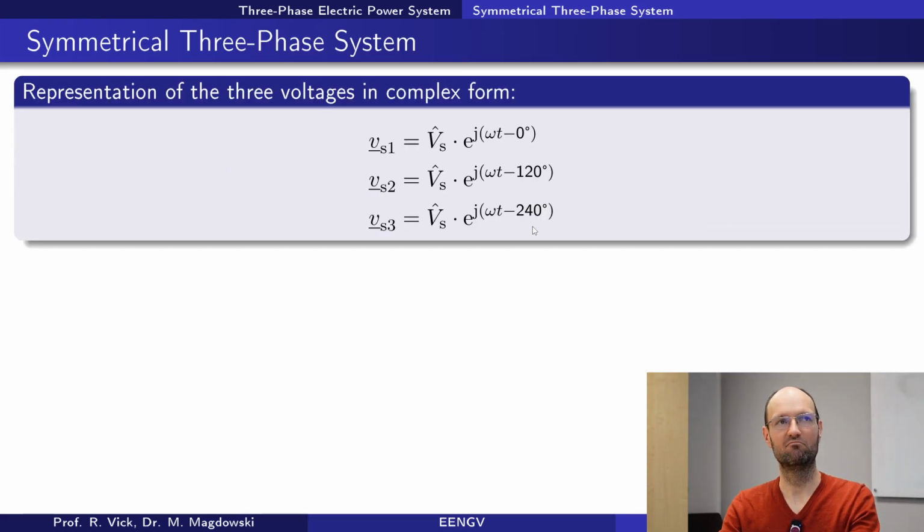So then, as we have done before in our single phase example, we can just rewrite them in the complex form. In the complex form, they also get some magnitude for this complex phasor, and we write the phase as e to j omega. Here it would be better, to be honest, to cut this omega t. This would be the rotating phasor, and we just want usual complex phasors. So I would cut the omega t here.